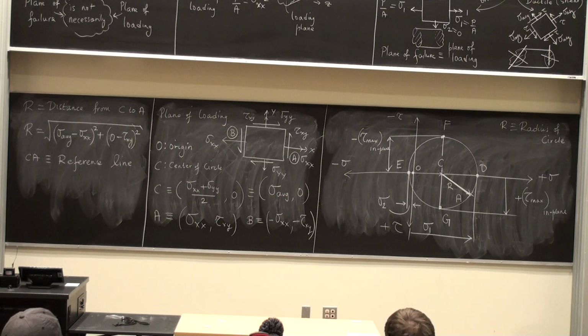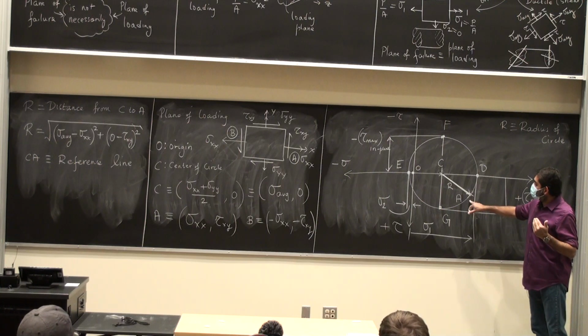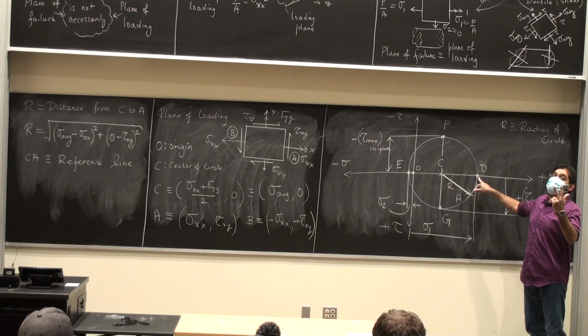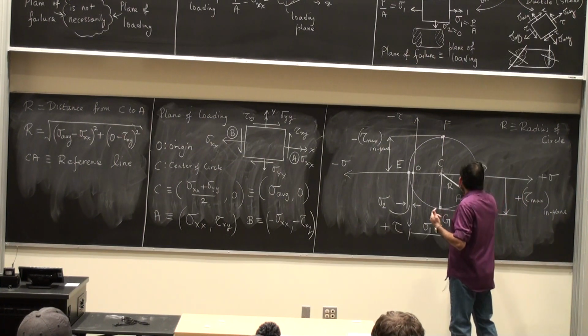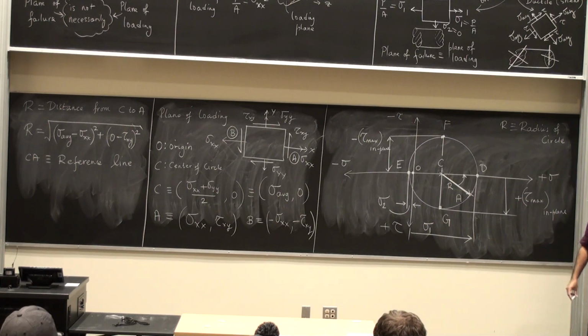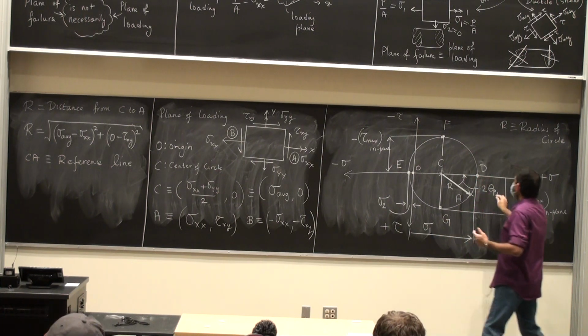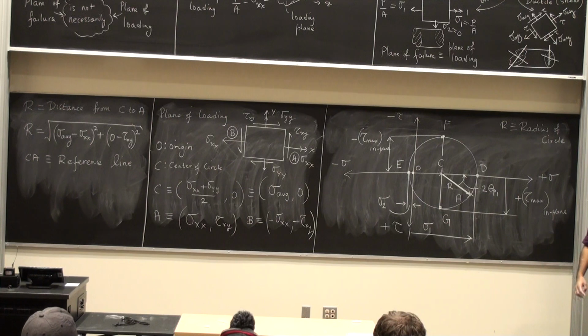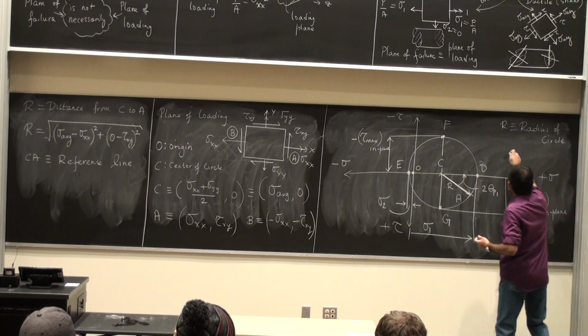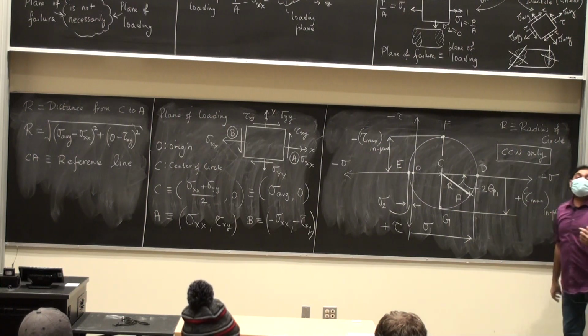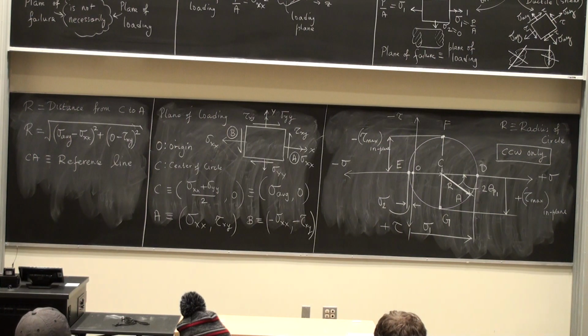And lastly, counterclockwise, from the line AC all the way to where the first principal stress resides is going to be 2 times the principal stress angle theta P1. And I'll tell you why it is 2 times in the next lecture when we solve problems. For the time being, just take it as a matter of fact. This is 2 theta P1. Always go counterclockwise. Every time we've done anything, the rotations have been positive counterclockwise. So I will always go counterclockwise only. Everywhere I go counterclockwise. Okay?